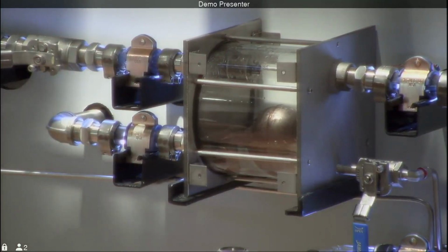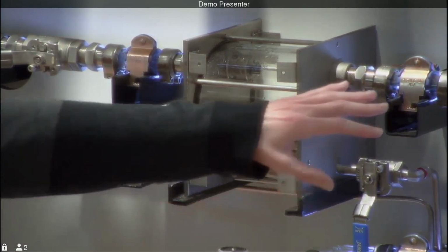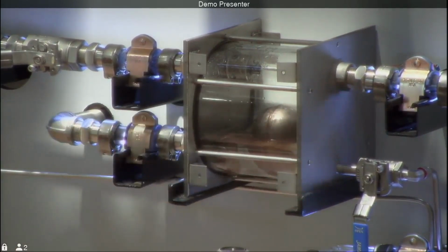Some of the disadvantages are that the valve is at the bottom of the trap, so that means it's prone to clogging easier than other types of traps. So that's something to keep in mind. You might want to consider having a strainer installed beforehand to prevent that.